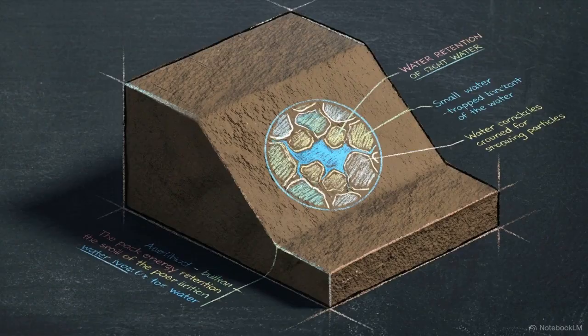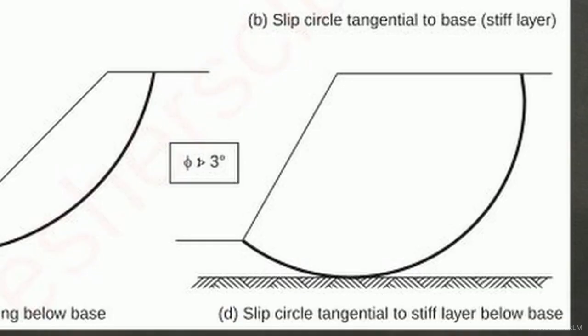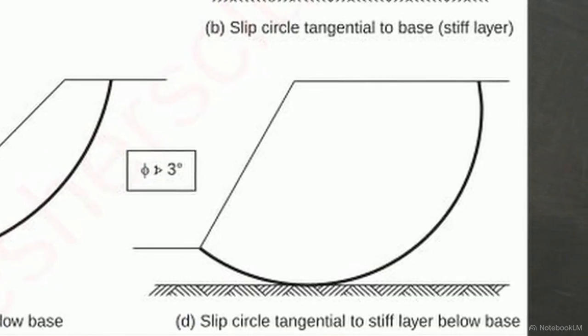Beyond volumetric flow and macroscopic failure, the flow net hides one more crucial set of data: localized pore pressures. When analyzing an earth dam or a slope, engineers need to know the exact internal water pressure at specific subterranean points to determine if a landslide is imminent. This technical diagram shows an earth slope's flow net. To extract internal pressure, we locate our target depth, point Z. We trace its intersecting equipotential line upwards. The vertical distance from this top intersection down to our target establishes the piezometric head.